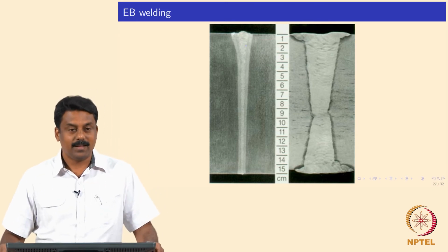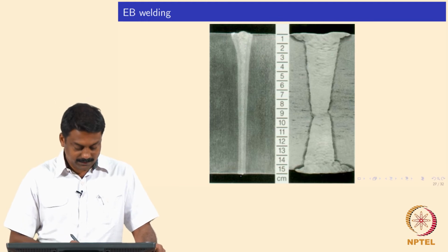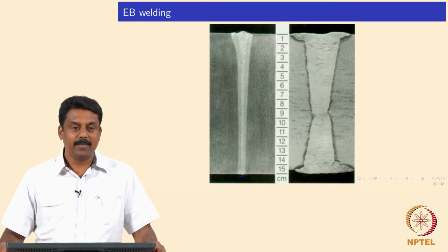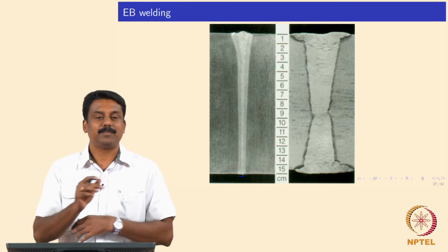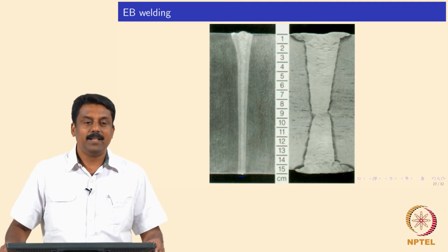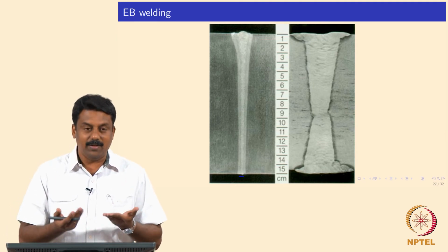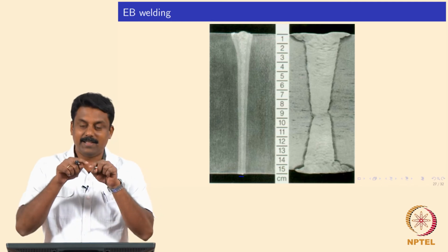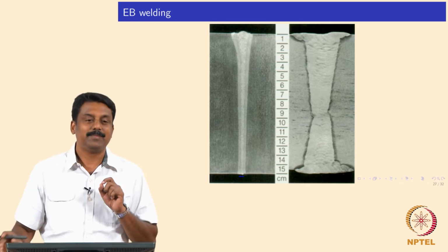Yeah. Sir, in case of laser beam welding, yesterday we discussed that sometimes the beam pressure is so high it might lead to a hole, like from here it will pass to the other end. Yeah, this is also a hole. This problem will always be there. That is a problem in electron beam welding. The beam pressure is so high, you always have a through hole, right? And then this hole has to be closed.